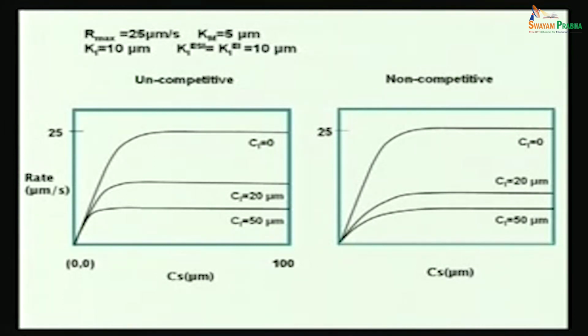By reducing the RPM. No, RPM, no, let's not get into mass transfer resistance at this point. Okay, the answer is this: instead of using one large reactor, replace it by several reactors. So if you have a reactor of say 10 hours residence time, replace it by 3 reactors or 4 reactors of 2.5 hours each.